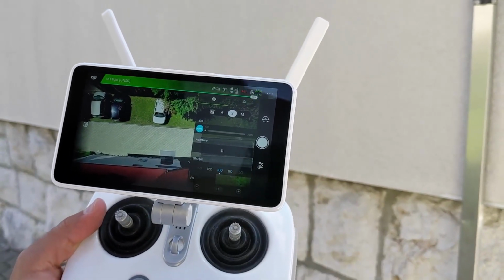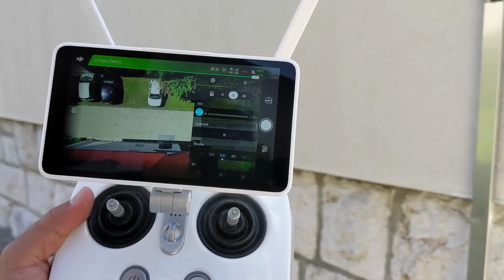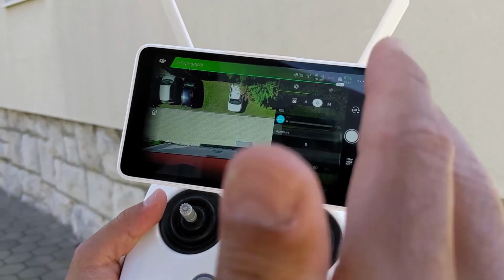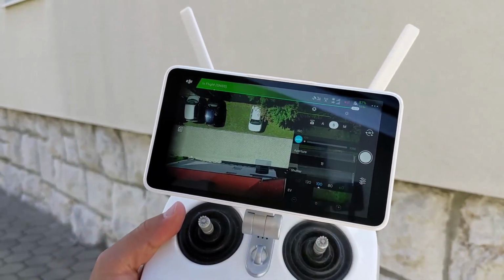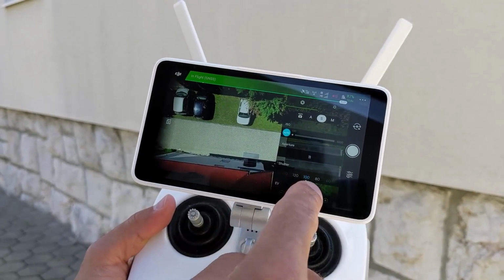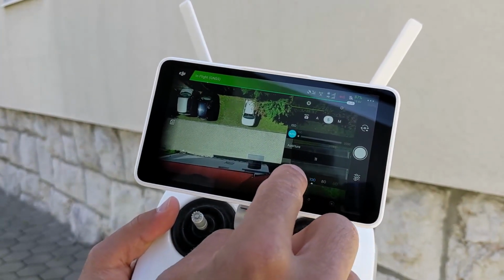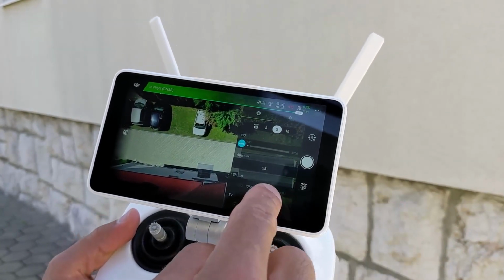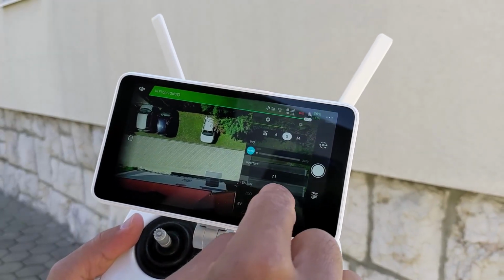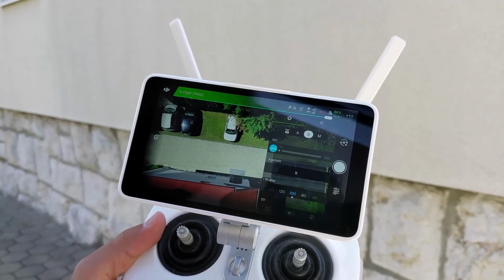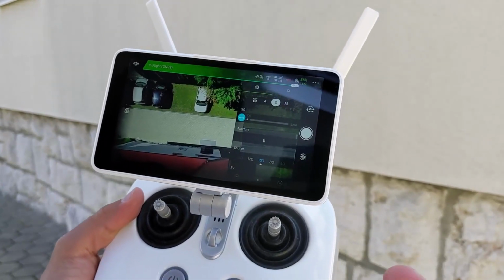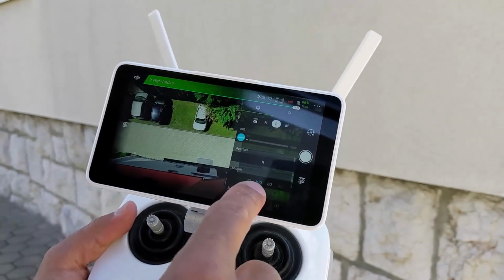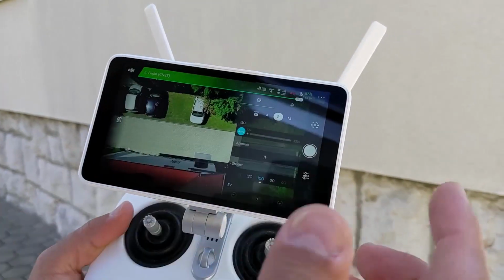You would definitely like to have an ISO value of 100, because this will give you the best accuracy of the model. The aperture can run from 2.8 to 10 or 11, currently it's 11, and shutter priority should be between 100 and 2000 or something like that, depending on the weather conditions you currently have. Never go under 100, because the image could be blurry, since you're usually capturing images during the flight. So take a value from 100 to, let's say, 2000.